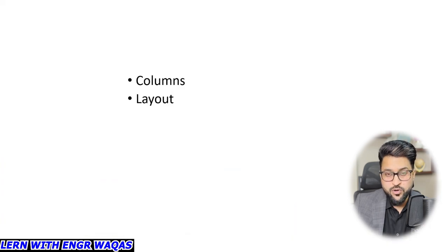So right now I'm going to open layout and switch it to the basic one, apply, and you can see that here I have the same basic layout, right? Okay, so that is how you can set your columns and work on your layouts. Right, layout is a very important feature. You have to add different kinds of columns: you need cost, you need the critical path method, you need many other things once you are done with different learning tools in Primavera P6. So columns and layout is a very important feature.